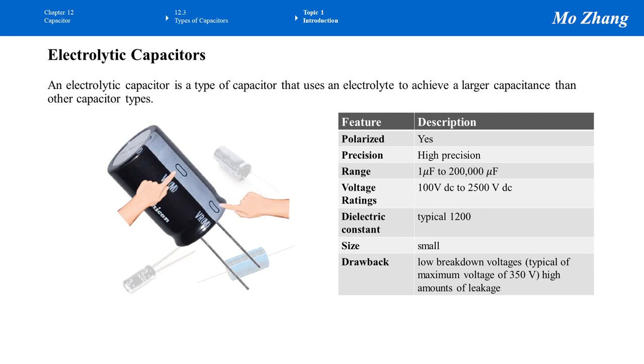If you look even closer, it has this sign. It is a negative sign, which means the leg this ribbon is pointing at connects to the lower voltage in the circuit. This implies this kind of capacitor has polarity. If the capacitor is connected incorrectly, there's a chance we can blow up this capacitor. So the key is that orientation is very important, since the electrolytic capacitor has polarity.